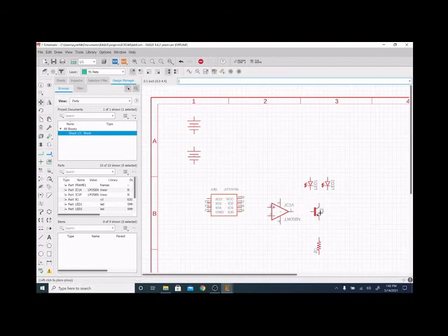This guy is the label for that transistor. I'm going to move it a little closer just so it's a little more readable. And I think that's actually pretty good. Okay. So let's use this net tool. The net tool allows us to connect different parts together. But one of the features of it is you can actually do what are called air wires.